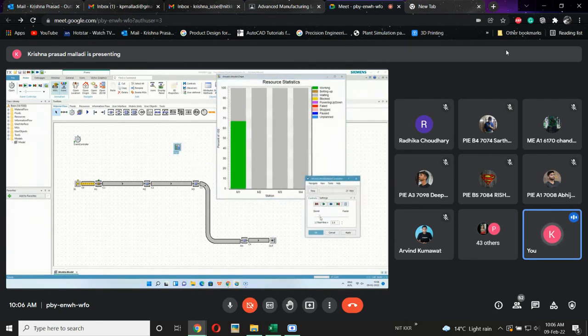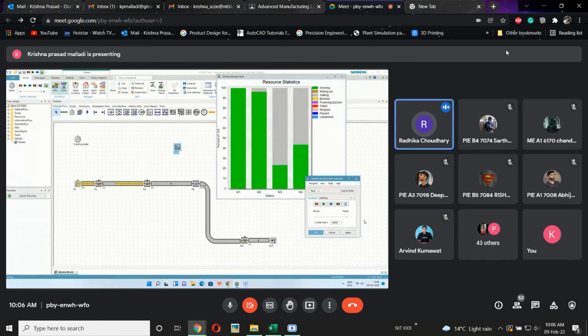I want to maximize the production. I want to increase the speed and check. Now will there be any blockage? Have you identified any blockage in this model? No, sir. But previously there was a blockage at M1. Why is there no blockage now? Because earlier the material reached M2 but was not in process, but now it is between M1 and M2 and has not reached M2.